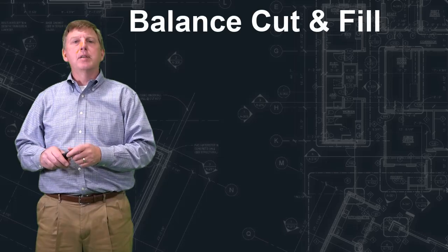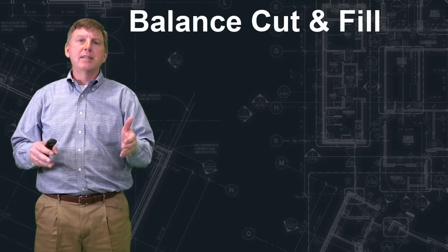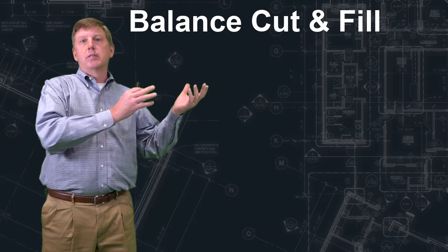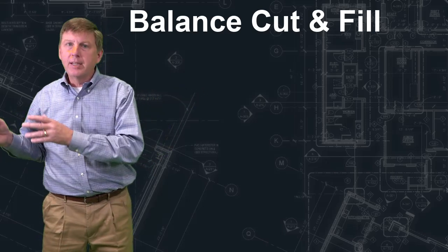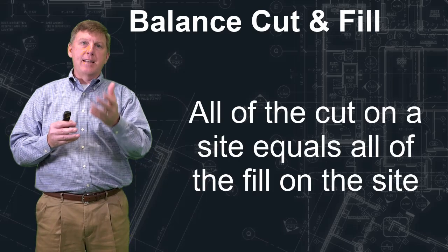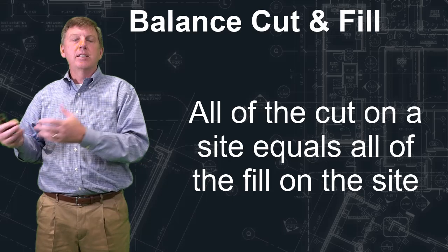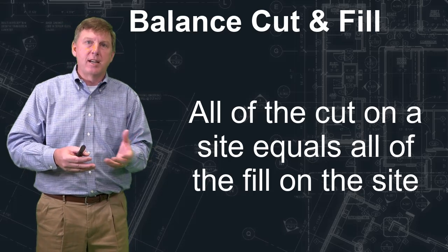There's a term that comes up often in grading, and that is the balancing of cut and fill. The goal is not to be hauling earth away from the site and not to be bringing earth into the site. That is balance, when the amount of earth that you cut from a site would equal the amount of earth you need to fill the site.